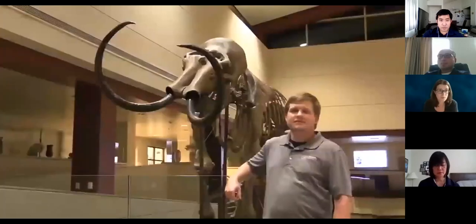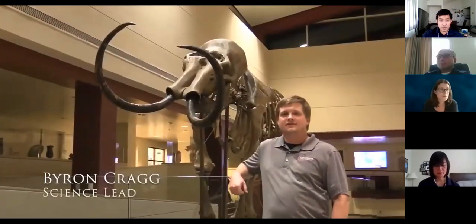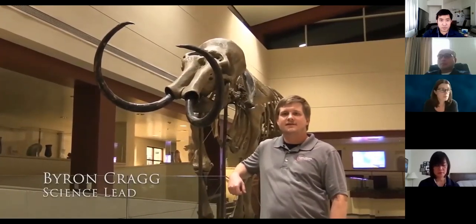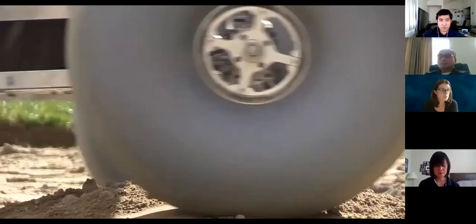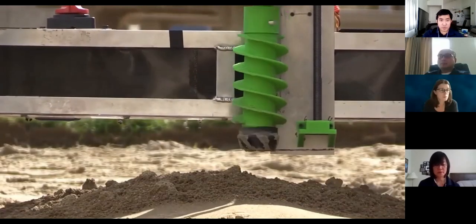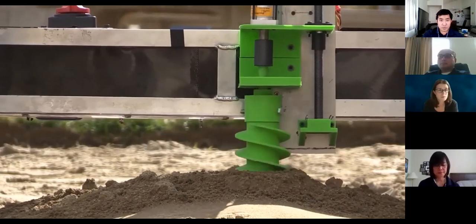For this year's science system, we have refocused our efforts on collecting a suitable sample for our life detection assays. This involved designing a hollow stem auger that is able to collect and store a sample down to a depth of 10 inches while preserving relative superposition.